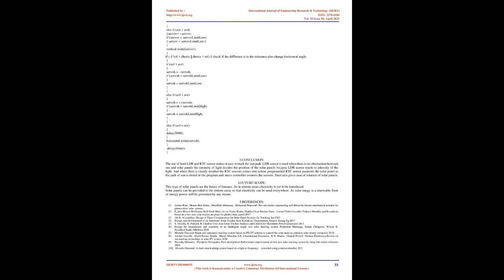D. Arduino. Arduino is a type of microcontroller. The purpose of the microcontroller is to control the position of the motor. The ATmega328P microcontroller is used. Arduino consists of 6 analog inputs and 14 digital I/O ports. Out of them 6 act as PWM signals. In addition to this, it consists of a 16 MHz crystal oscillator and a USB cable through which the program is dumped. And Arduino gets powered by the power jack. Advantages of Arduino are low cost, robust construction, and platform independence.